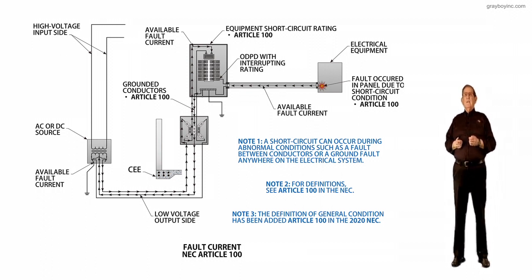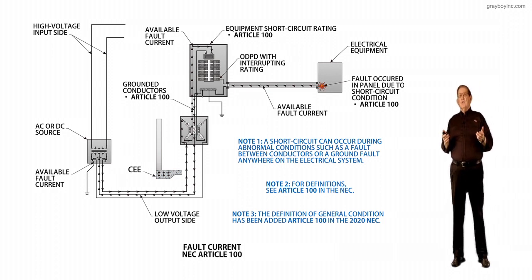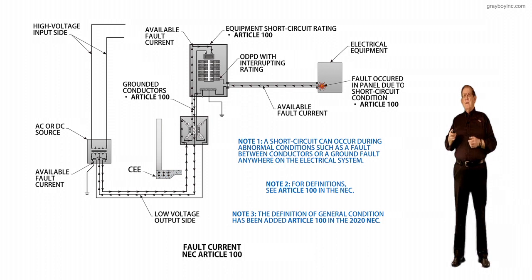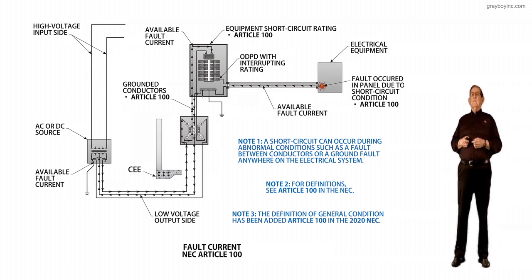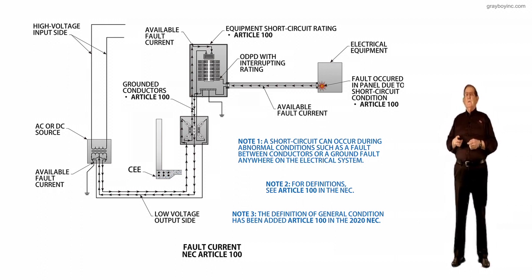So thirdly, look at the illustration. Well, it includes the conductors from the main panel over to the electrical equipment. And the title here is available short circuit current. Now, the low impedance path there is based upon Table 250.122. For example, if you had a 200 amp breaker, then you would need a number 4 equipment ground pulled in there if it wasn't metal conduit and so forth, or you wanted redundant grounding, however you wanted to do it. Notice Table 250.122 would size that.